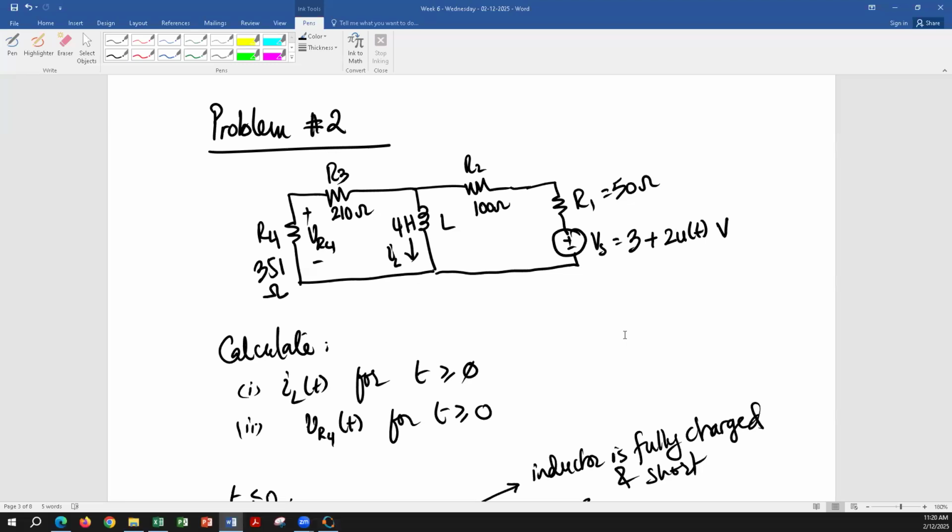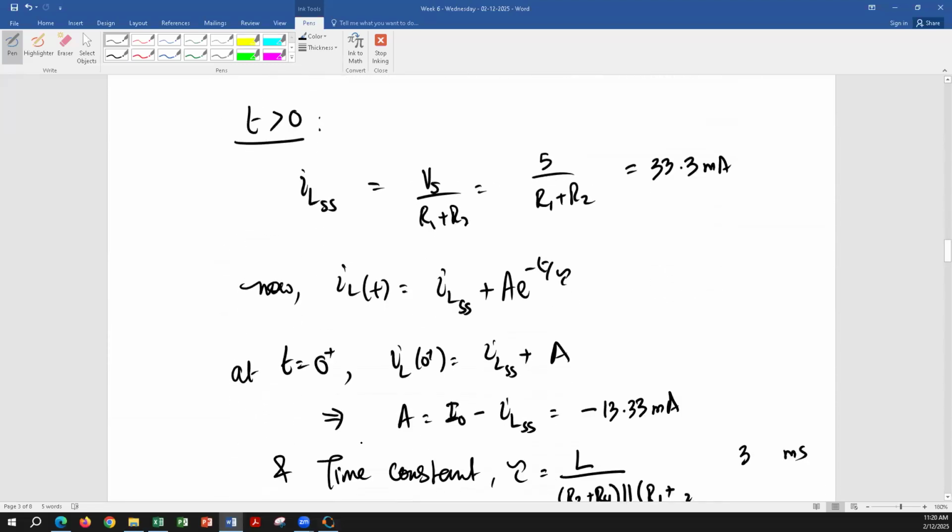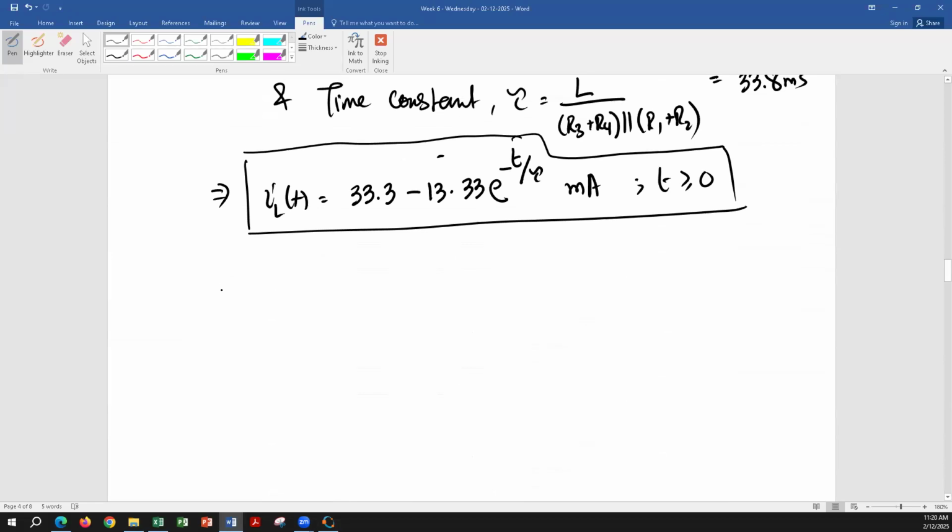Excellent. Now, in this case, since we have a source and the source is supplying current, the voltage is not really changing direction. It's still going to be VL. It's just the level is changing from one energy level to the other, but the source is still supplying the current. So we will still use this equation. If the voltage does change direction in a source-free circuit, as I said, then usually we take negative L diL over dt. But in this case, we're just going to take L di over dt. So let's go ahead and calculate the inductor voltage.